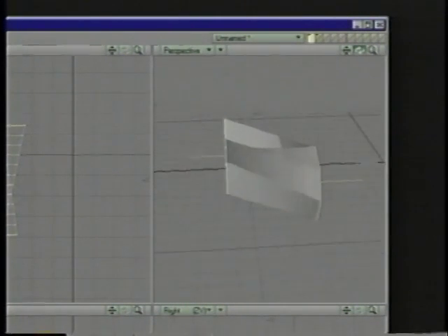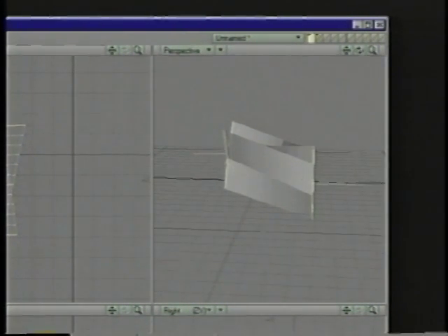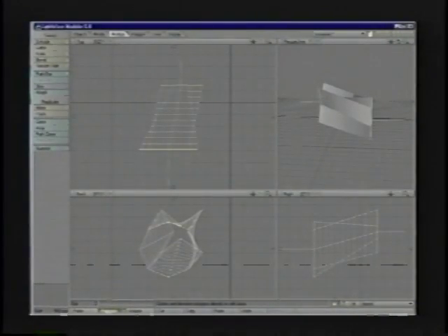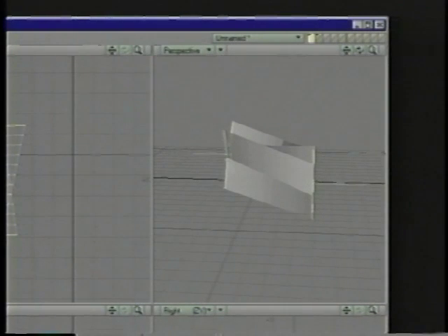And the difference between this and skin obviously is it gives us the ability to put multiple segments between the two objects instead of just having it skin across both polygons as one sort of mesh. The other thing to keep in mind with the morph is that your morph target from one disk to the next have to have the same number of points, or else it won't be happy and it'll complain to you.